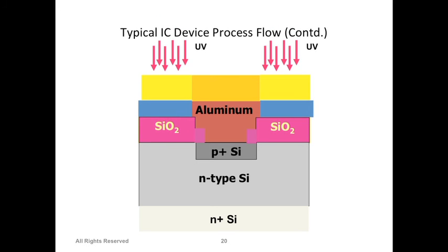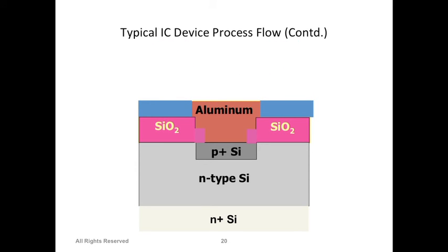So photoresist, then mask, and then we expose the area where we don't want aluminum. With the photoresist development and all that, the photoresist will go away from this area, then we'll do the aluminum etch. With the aluminum etch, you should be able to remove aluminum from these two sides, and it will stay only where you want it to be. And this is just one cross-sectional view, but on the top it looks like you can make any wires, electrodes, or interconnects on the surface. So this is the general process for how we can start building a transistor or any other configuration on the surface of semiconductors.